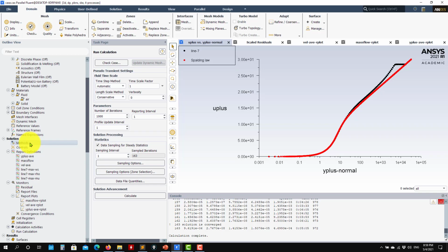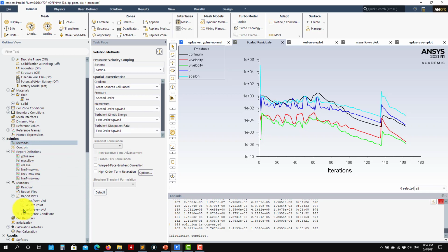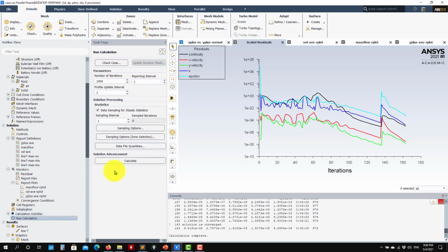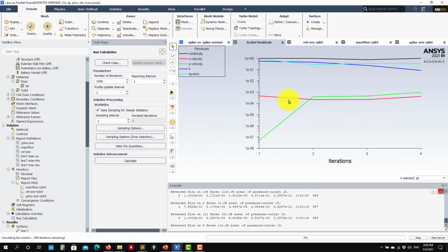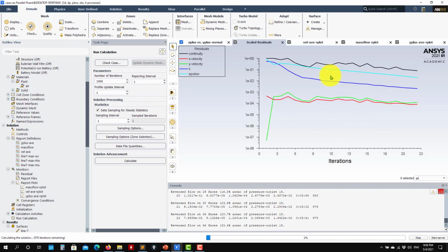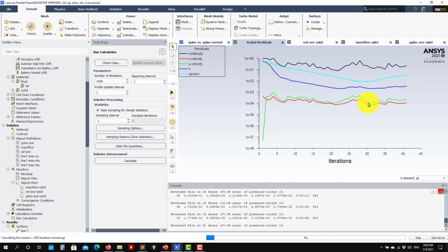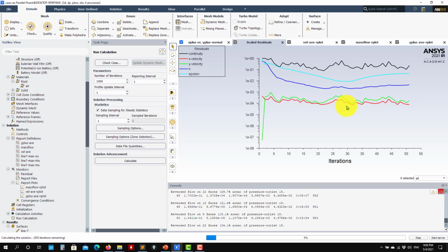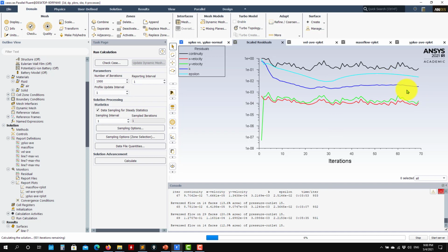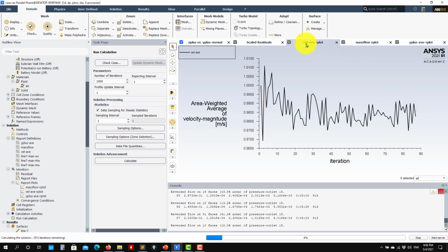So finally, the last thing that I want to show you, let me go here and use this simple method, okay? And just to show you, initialize, just to show you that the cost per iteration in this one is much lower. As you recall from the previous coupled solver, each iteration takes some time. Instead here, it goes faster, but the convergence rate tends to be slower. So it will be a compromise, okay? The coupled was going down relatively fast. This one is kind of stalled there, okay? But slowly it will go down.